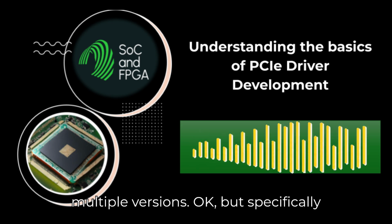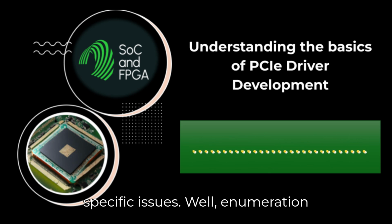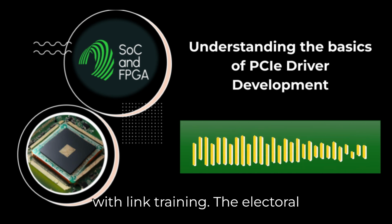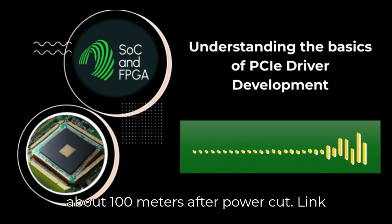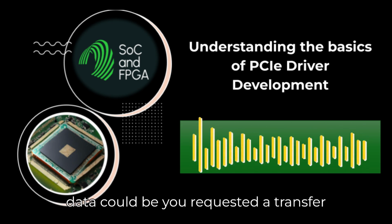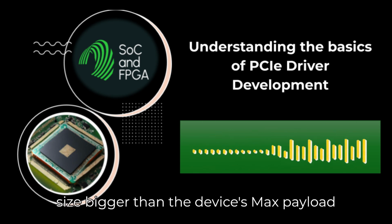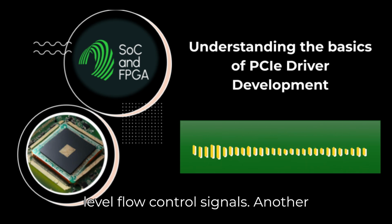Okay, but specifically for PCIe, what goes wrong there? PCIe-specific issues. Well, enumeration failures are common. The device just doesn't show up. Often it's a problem with link training. The electrical handshake fails, maybe times out. It has about 100 milliseconds after power good. Link training again. Yep. Then there are DMA problems. Data corruption, missing data. Could be you requested a transfer size bigger than the device's max payload size allows, or maybe issues with low-level flow control signals.